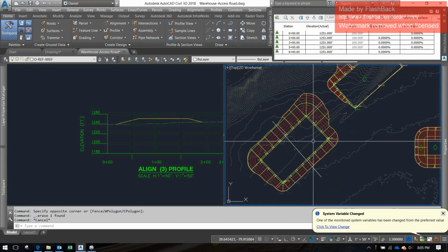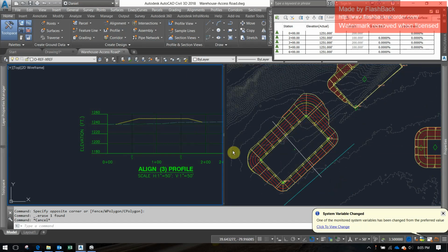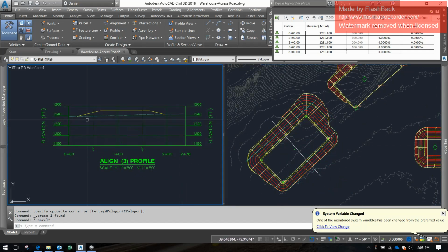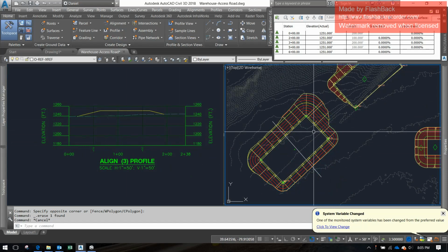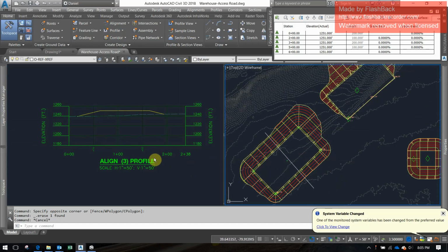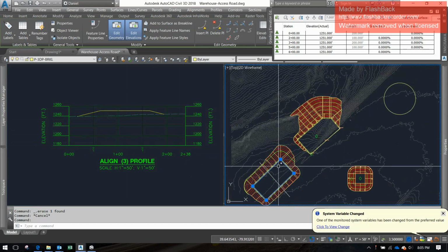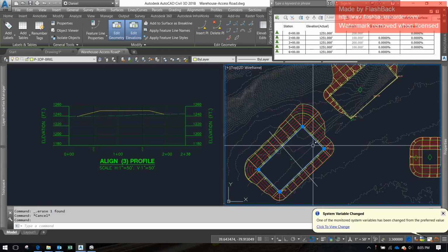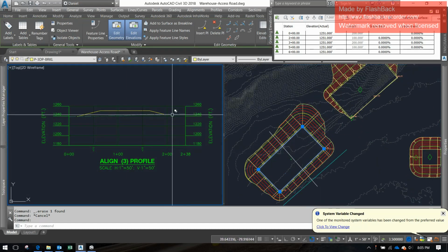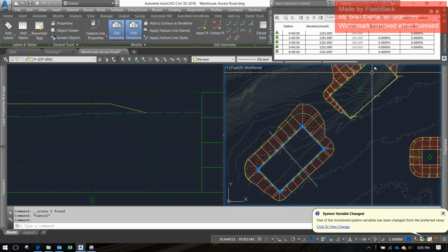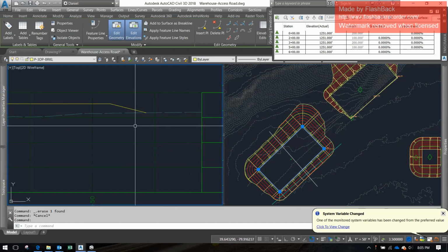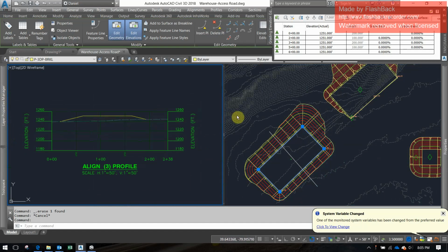So what we've done is we've graded a pad here that is going to be conducive to a truck ramp running up it. I'm going to bring these elevations back down because I don't like how big an impact my site has. It's unnecessarily high, right? So I don't need my truck coming along this way to have to climb 7 feet additional just to climb my pad here. So what I'm going to do is drop these elevations back down by selecting the feature line and just hitting this drop down arrow.